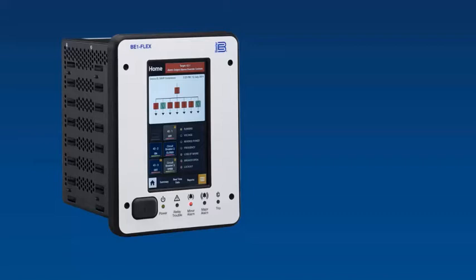Today we're going to be talking about trip circuit monitors. Trip circuit monitors have been implemented in digital relays for a number of years, and the way they operate is they inject a small amount of trickle current through the trip coil of a breaker to ensure continuity of the wiring and the trip coil itself. It's not actually monitoring the contact itself within the relay, it's monitoring the wire and the breaker trip coil.